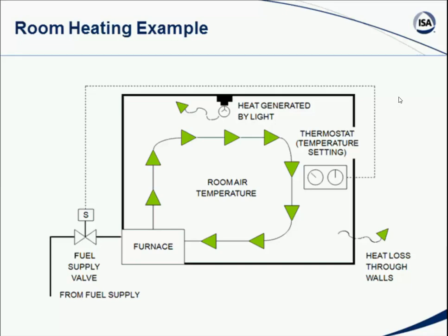And this doesn't seem all that complicated. But actually, if we really break what we're trying to do here down and think about some of the considerations, there's some very serious aspects we have to deal with in order to do this thing properly. One of the obvious points is that we've got a large room here, or maybe we have several rooms in the house, and they're all being kept at the right temperature by a single measurement point. I don't know about you, but in my house, my thermostat's in one particular room, and that room is always rather comfortable. And I've got other rooms that are always a little too hot or a little too cold because it's not making the measurement there.